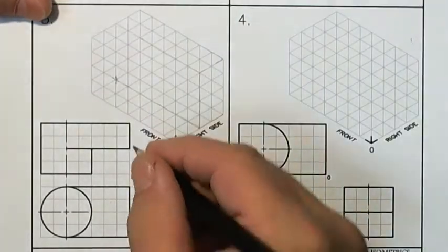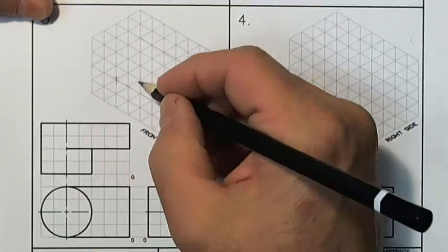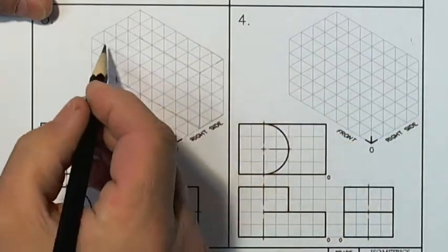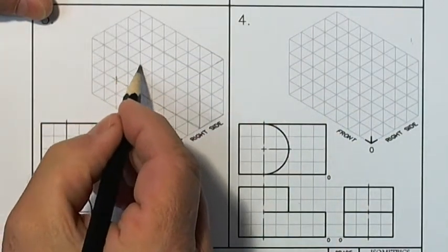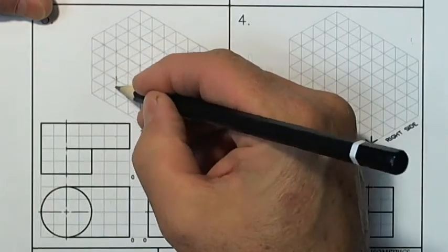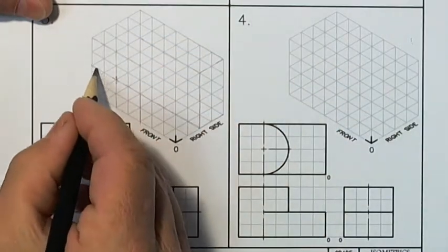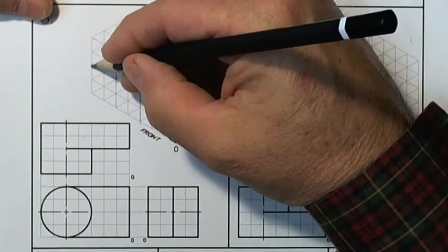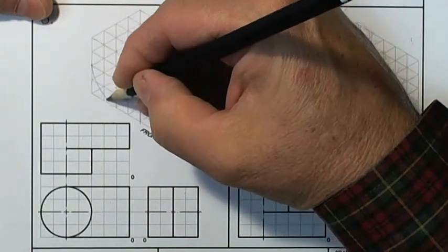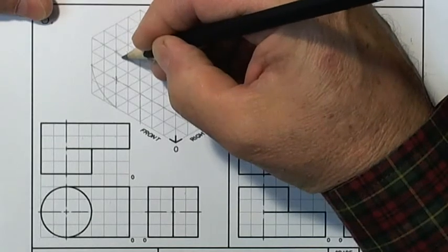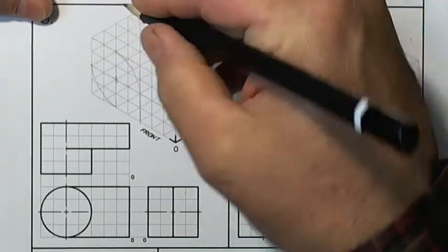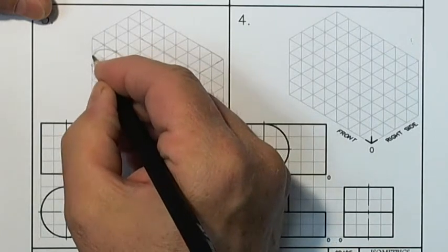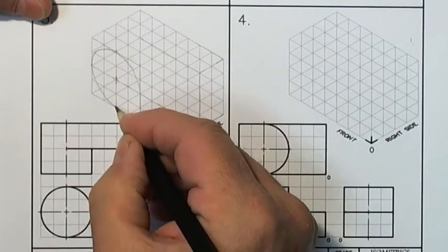That's the center mark. The radius is 2. So very lightly, I'll put my parallelogram in for the front face. Then I will draw my flat arc, my other flat arc. I'll draw my rounded end,